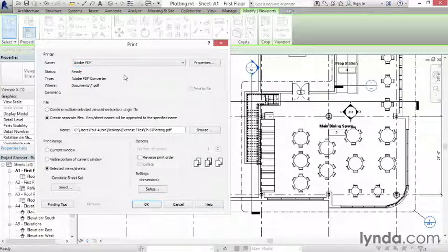But Revit can print to any device: a laser printer, an inkjet printer, a full-size plotter. So you want to choose the device that you typically print from. And if necessary, you click over here on the Properties button and configure the device-specific settings for that device. So naturally, the options that would be available over here on Properties will vary depending on what you choose here.